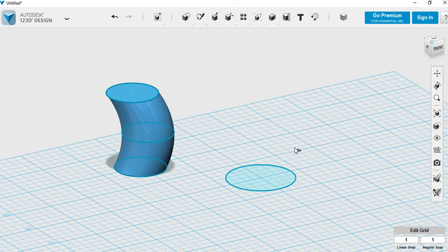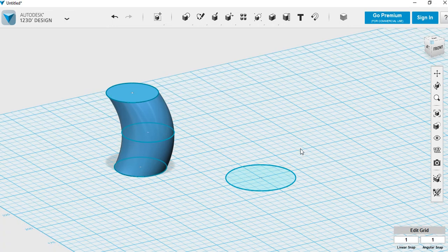And every time you draw the circle, you have to press enter to commit the sketch to the screen. And then you select the bottom circle. To select, you must go just inside the circle. You see where my pointer is now. The circle will glow green. Click and it will turn blue.